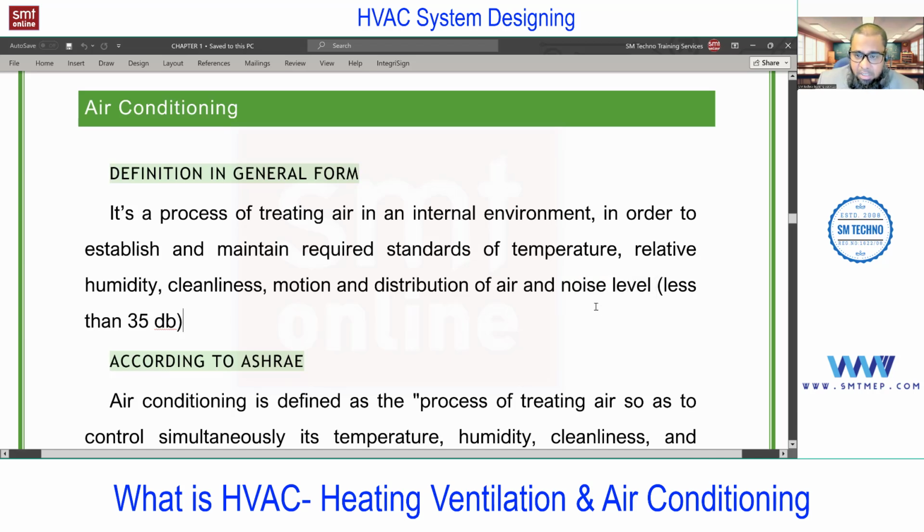Suppose you are supplying the air with higher velocity, and as the velocity increases, the noise increases. Both are directly proportional. This part is also important. We'll discuss it at the time of duct designing. So noise is also one parameter to maintain, especially for human comfort. Again, this is not applicable, or you can ignore it for process control, because the machine will not get disturbed with the noise. Okay, depends on condition.